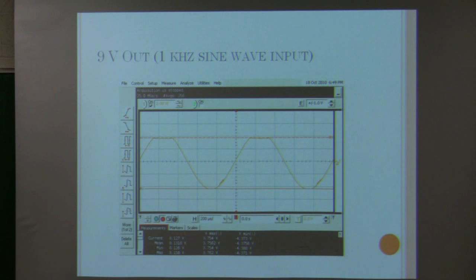My battery voltage in this case was, I believe, about 9.6 volts. So I was trying to put out that. So it's 9.6 and then minus 0.7 twice. You're trying to put out more than it can. You pretty much chop off the top and the bottom of the waveforms. So you're putting in something that looks like this, and you're getting this out. That's no good.